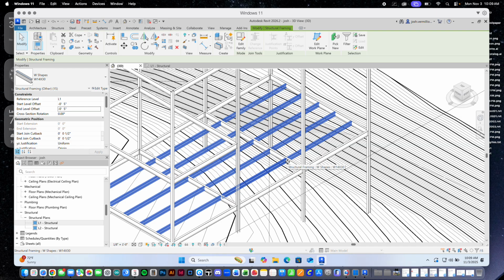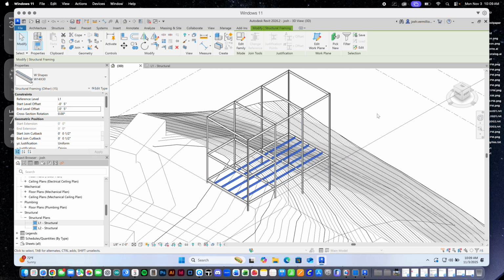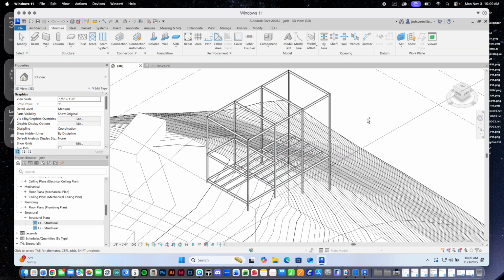And again, because of course, we needed to also change their reference point, right? So right now they're just sort of framing into the extents box of our girders, and we actually need to bring them so that they frame into the webbing of our girders. So we will do that here in just a second. Is everybody able to follow along? So here's what I did, and I'll just go ahead and undo and show you again.